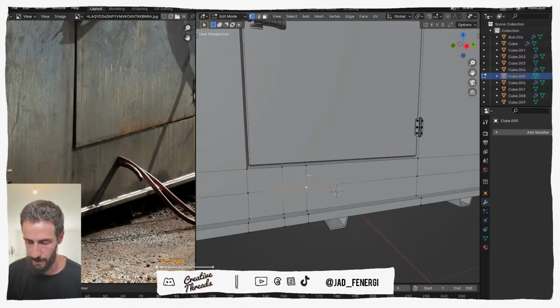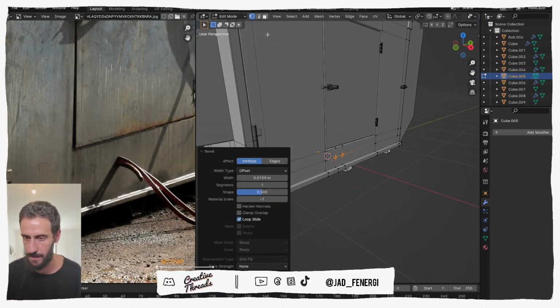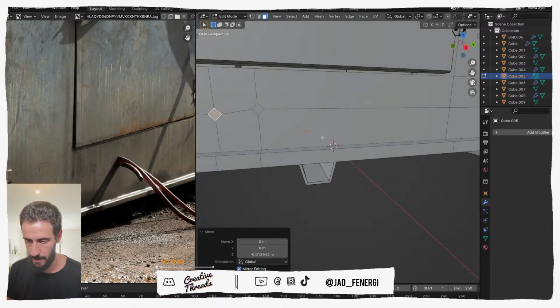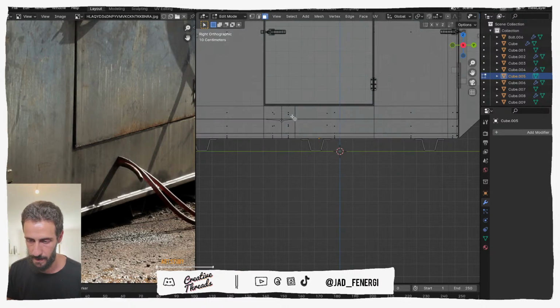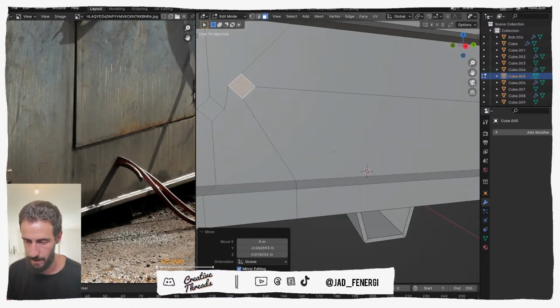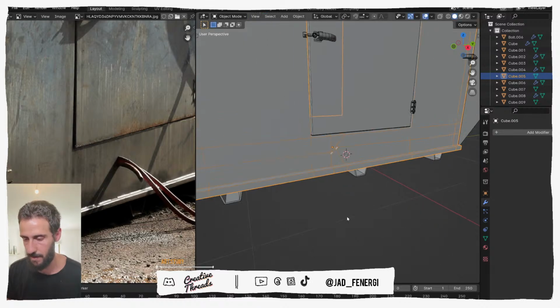Then the easiest way to do it is just to Control Shift B. Make sure they are just squares instead of circles, because it's gonna be too small anyway to notice whether this is a square or a circle. We can move this down a bit. We can move this here, doesn't really matter. And we can extrude them to the inside. And that's it actually.